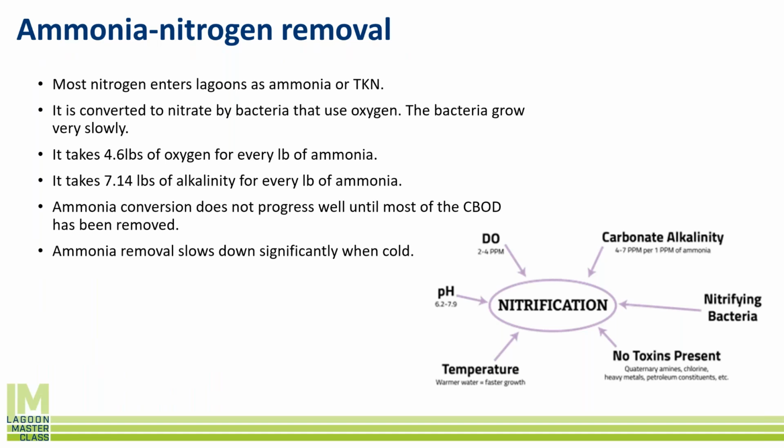And then lastly, do you actually have bacteria in there that can do it? So do you actually have nitrifiers? Sometimes if you have a kill where you have a lot of toxins, we actually have to put new nitrifiers in there. And believe it or not, there are companies that sell nitrifiers. We order them by the gallon. And sometimes we have to bring those out there and pour them into the lagoon because we killed off our system due to toxins that have come in from one of our clients.